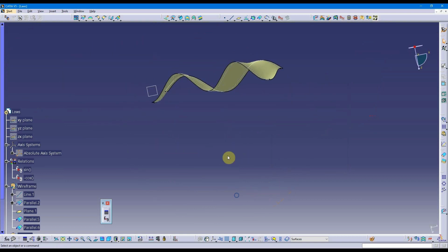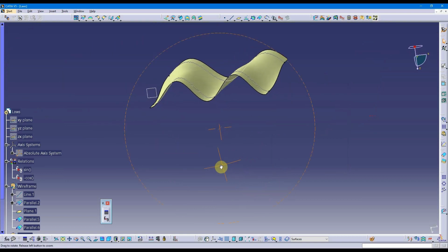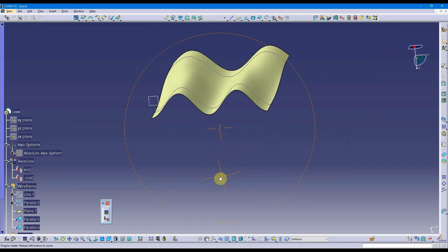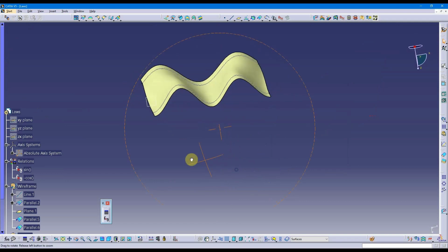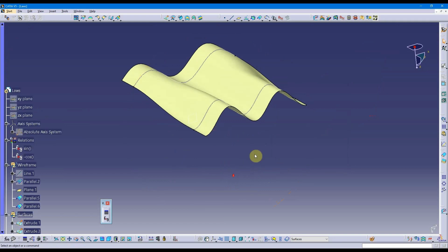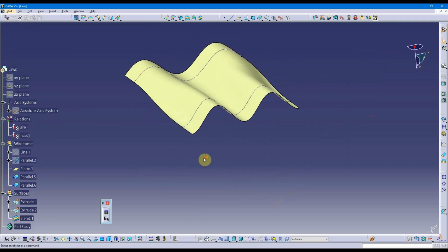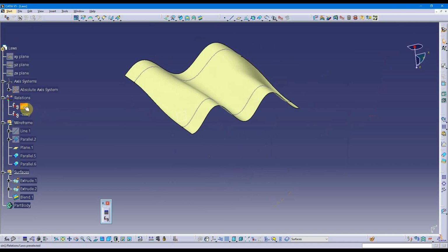Notice how I've got a lofted surface between a sine curve and a cosine curve. Again, interesting, right? Makes it interesting. You can do the same thing with a loft, but the key thing for this demonstration is showing how to do the laws with sine and cosine, and making sure your units are correct. And if you get that warning message about your units not being correct, make sure you fix it. It's going to make a more robust model in the end.